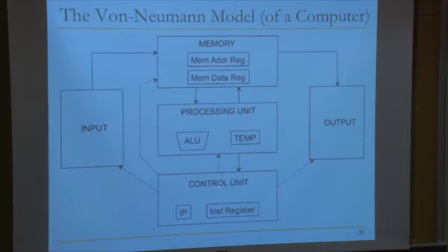And you have some logic in the data path that decodes this instruction register and generates control signals for the next stage of instruction processing. And then the control unit moves to the evaluate address stage, which is done in the data path somewhere here, which could be done through the ALU. We will cover that. And then the control unit moves to the fetch operand stage, depending on the instruction. Some instructions may not really need an operand, right? And then the control unit moves to the execute stage, which is done in the processing unit.